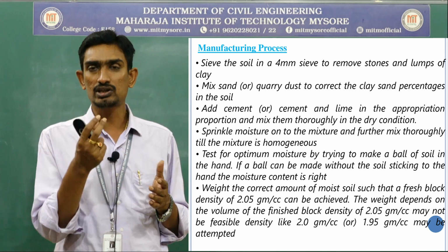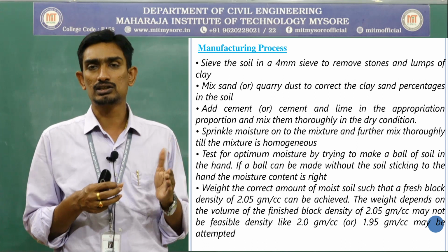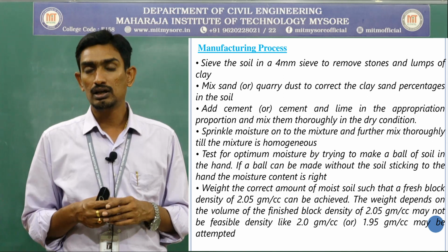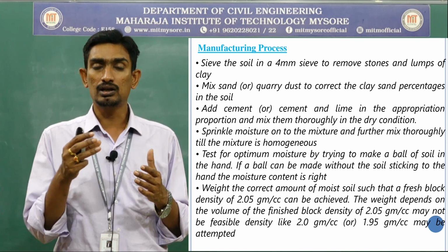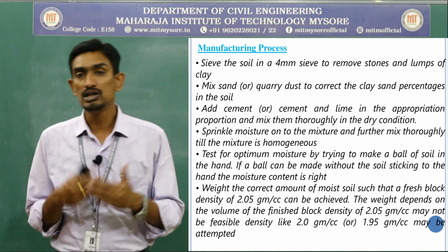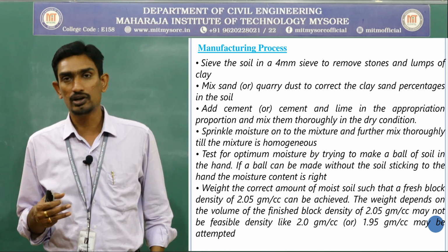If that mixture does not stick to the palm of your hand, then I can say it has attained OMC, or optimum moisture. If that particular sample is sticking to your palm, then we need to do the mixing part. That means the water content is more. We need to manipulate it. Did you get my point?